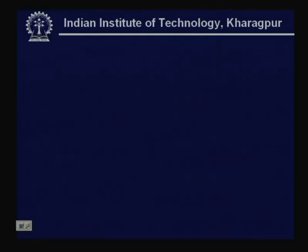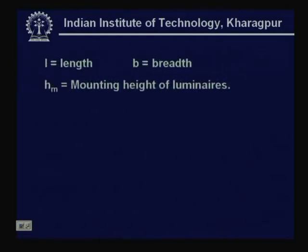This is the guideline. Now, how do we arrive at the room index? Because I said the room index is the one based on which the CIE guidelines give us the number of luminaires that may be located. So, the first thing we will see is the mounting height.